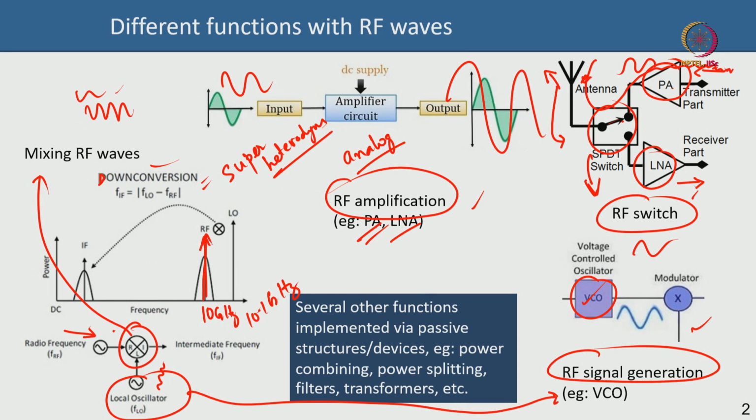It will create a 10 plus 10.1 gigahertz signal, which is a 20.1 gigahertz signal, and it will create a 10 minus 10.1 absolute value, which is a 0.1 gigahertz signal, or 100 megahertz signal. It's much easier to operate at 100 megahertz and do all kinds of signal processing on it. So you're going to retain that 100 megahertz signal, and you're going to reject that 20 gigahertz signal by using a filter.